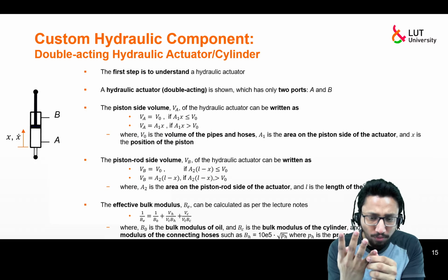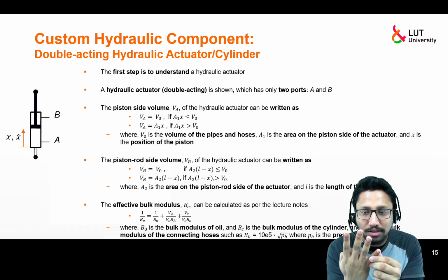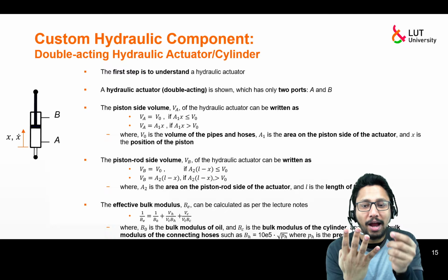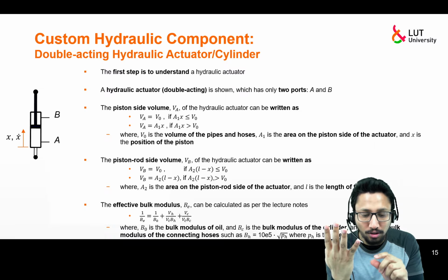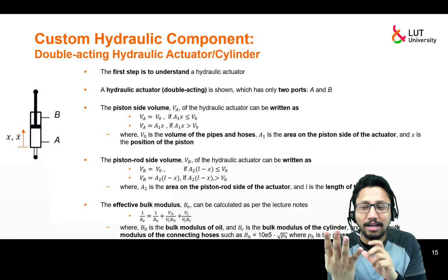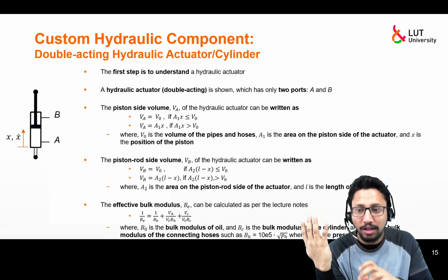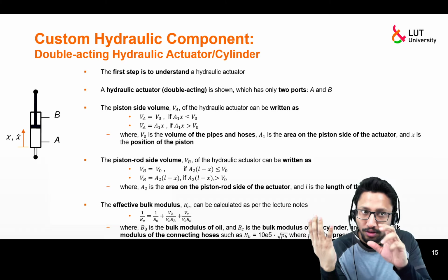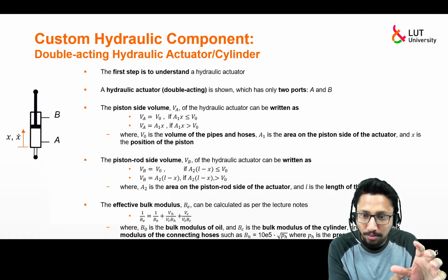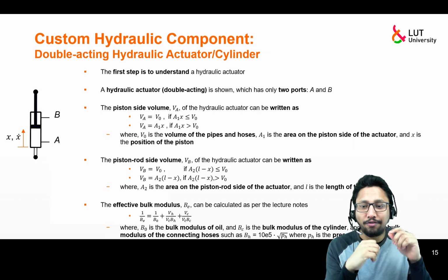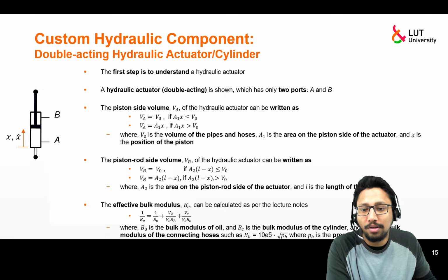So that's what we are interested in: the force coming from the hydraulic actuator, because this force we will feed back to the mechanical structure, across the joint which is connecting the rigid body cylinder and the rigid body piston. Across that joint we will feed this force coming from the hydraulic actuator.